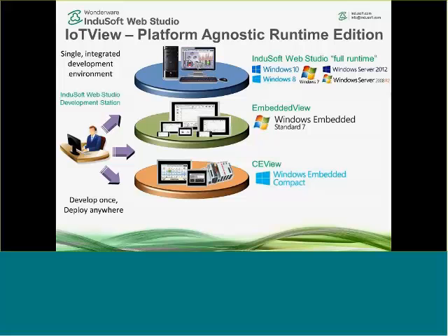Platform agnostic runtime. Well, let's talk a little bit about where and how InduSoft runs on these different environments. You can get InduSoft Web Studio, or what we call our full runtime, to run on any of the desktop or server operating systems that are put up by Microsoft. In addition to that, we have the Embedded View license, which is for Windows Embedded, and CE View for what's been known as Windows CE, now Windows Embedded Compact.